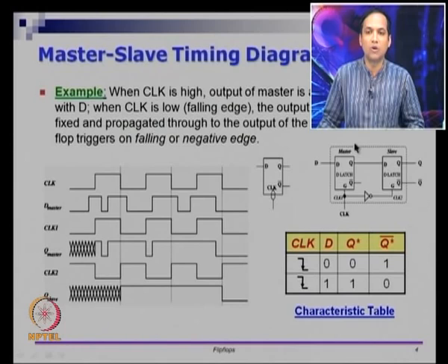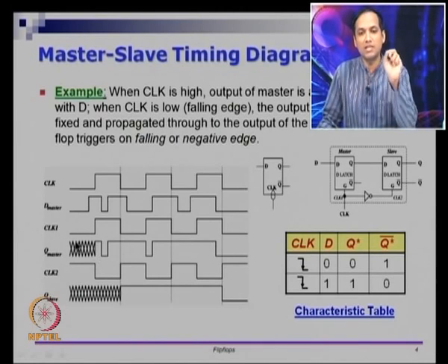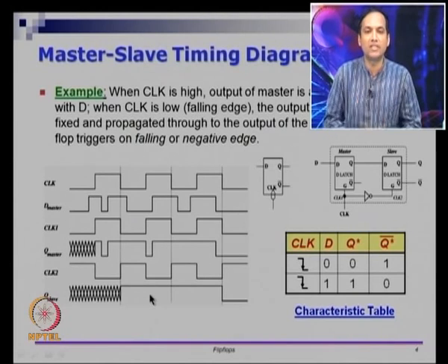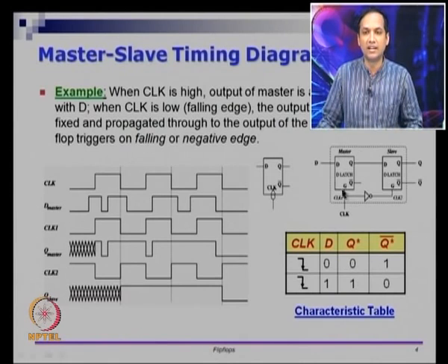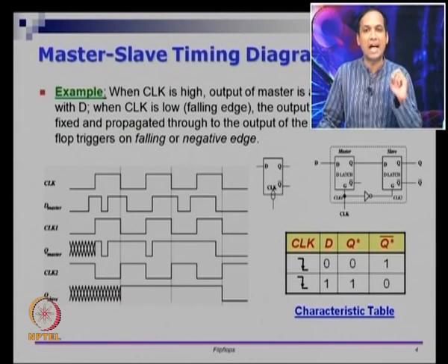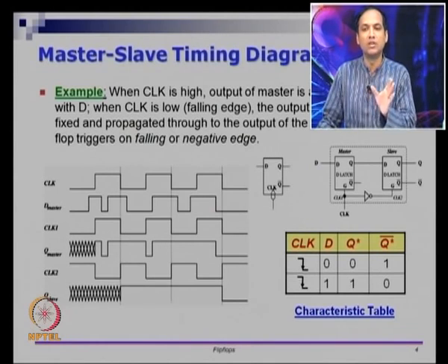If you look at the output of this whole circuit, the Q versus D relationship, Q has far fewer transitions than D. This is not the goal here. However, something else has happened interestingly. I am now going to make a claim and we will verify that with the picture. The claim is that this circuit, this overall black box, which I am going to call the D flip flop, is going to sample D only at the negative edges of the clock, and it is going to keep the value everywhere else.